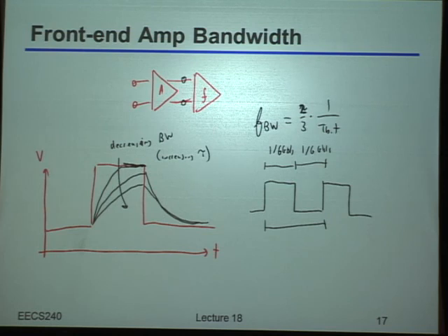Okay, so the Nyquist rate is indeed always half of the data rate, at least for the simple kind of system that we're talking about here. However, nonetheless, you do indeed need, or at least this first order rule of thumb tells you, you do indeed want bandwidth beyond that Nyquist rate. Because what's really happening is that in time, you want to make sure you settle sufficiently to actually get a very precise sort of value at the end of the day. Or rather, so you don't lose very much of your signal due to that finite settling. Make sense to everyone?